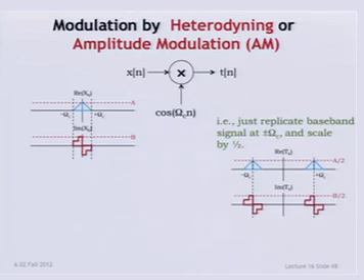We've seen last time what happens when you multiply by the cosine. You take the spectrum and you replicate it at the locations of the carrier. So if your carrier frequency is omega c, here's your frequency band going from minus pi somewhere there to plus pi somewhere here. You've got plus and minus omega c, the carrier frequency.